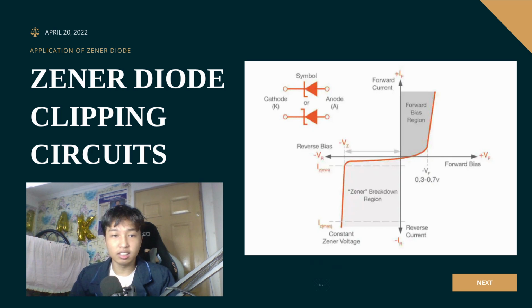The last type of clipper is biased positive clipper and biased negative clipper. When a diode conducts, the negative half cycle of the output waveform is kept to a level of V bias minus 0.7 volt by reversing the diodes and battery bias voltage. By adjusting the bias voltage of the diodes, a variable diode clipping or diode limiting level can be achieved.